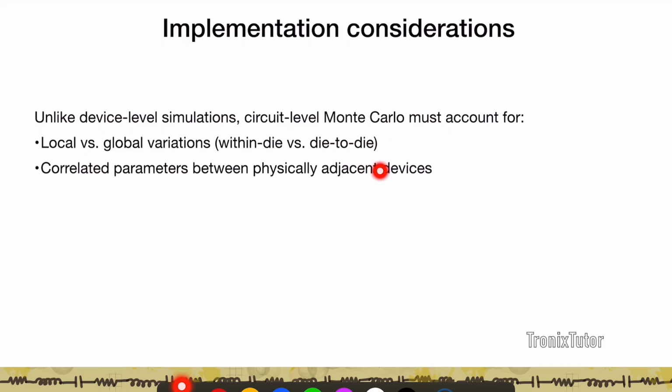So you begin to see that if you're doing Monte Carlos, you need to account for layout in your picture. If two transistors are next to each other, they're going to be correlated more than transistors that are, say, a few pitches apart. This is why, for example, in a differential pair, we tend to keep those two transistors as close together as possible, because they're going to be correlated as much as you can.